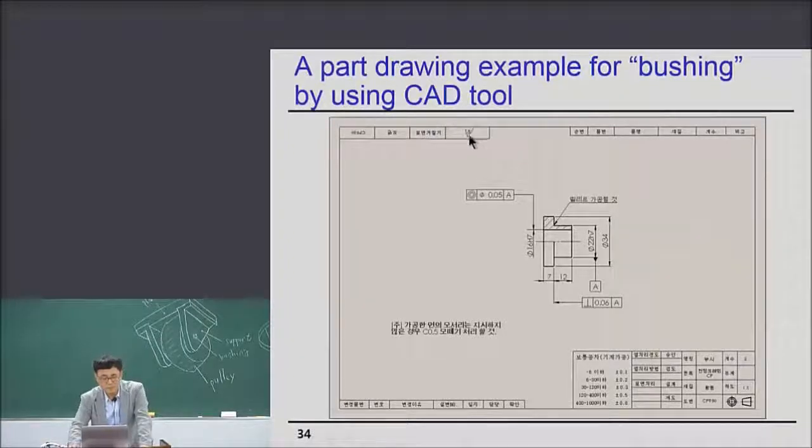And what is it? Surface roughness. It's 1.6 that is given. There is no specific surface roughness designated, but by this surface roughness placing, you see, all surfaces have to be machined with a surface roughness of 1.6. Okay, 1.6. So it should be done by grinding, maybe. It's not lathe and general milling. Maybe 1.6 surface roughness would be impossible with those.